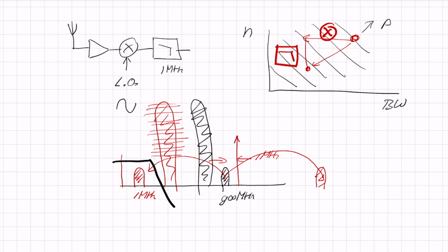And the amplifiers are there just to make the signal so big that the rest of the circuits don't add their own self noise, so those circuits can be low power. By doing this analog pre-processing, we can really relax the ADC demands, and this way the analog to digital converter becomes feasible. So by adding amplifiers, mixers and filters, we can make many more signals digital than we normally can. Okay, let's have a look at how these blocks work.